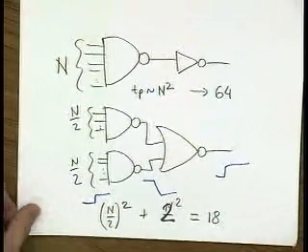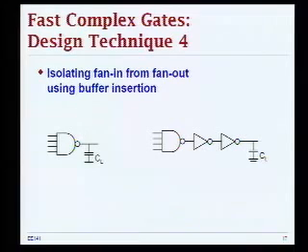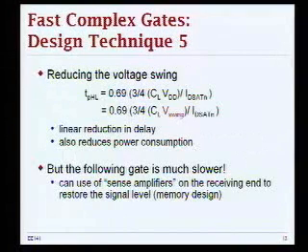All right. And also, finally, this is another technique for which I have an illustration over here. When you have a large capacitance, we already know, we just insert a buffer, right? It's good to distribute the effort into many stages. Basically, just gradually develop the voltage on that final output node.